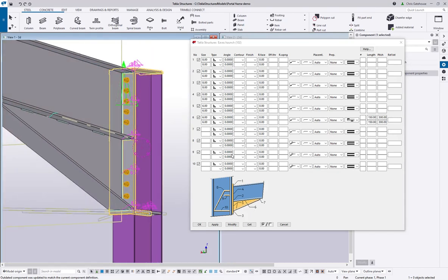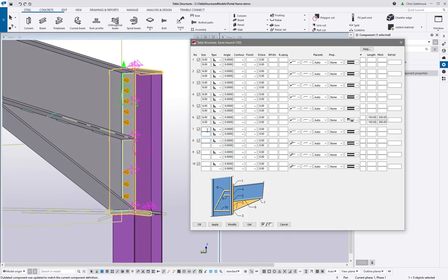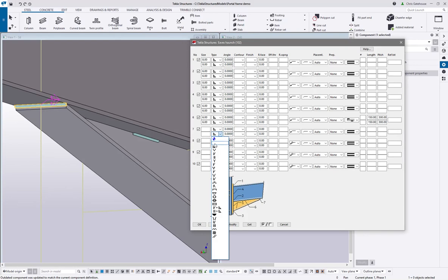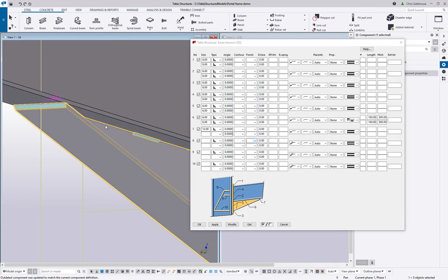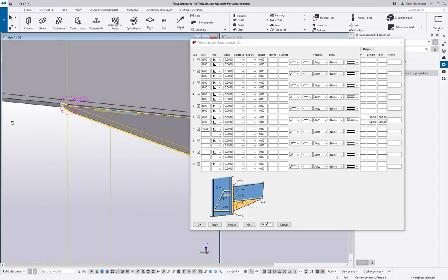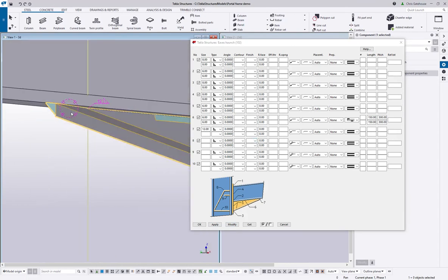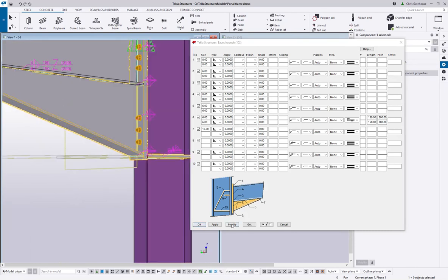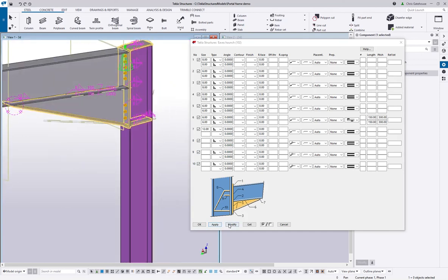And on the end of the haunch, which is number 7, we need to have a fairly robust weld. So let's say the 12, like so. And obviously that's going to be a single-sided, because you're not going to be able to weld inside that little gap there. So we'll put a decent weld on there. Okay. And then 8, 9, and 10 are your stiffener weld specs.